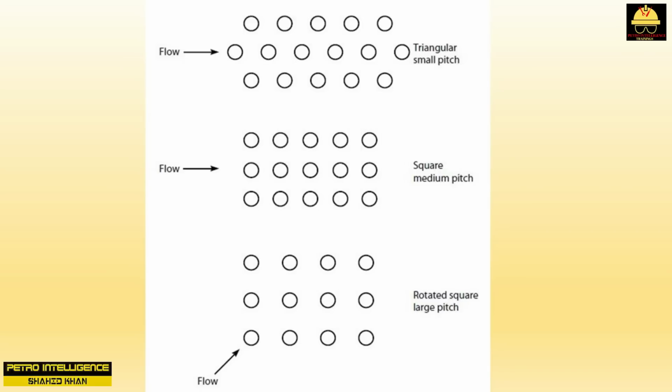The second example shown in the picture is 0.75-inch tubes, also set on a 1-inch spacing. But this time, the arrangement is a square pattern. This pattern reduces the number of tubes in a shell of a fixed ID. Also, less turbulence is created by the tubes. Some fluid may flow between the tubes without encountering the tubes at all. All this reduces heat transfer efficiency. But hydroblasting between the tubes is usually possible, depending on the extent of tube bending and twisting.